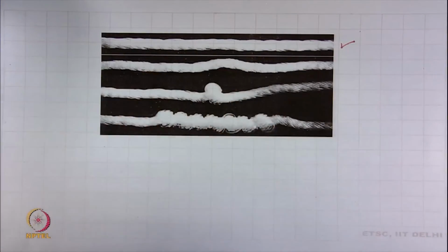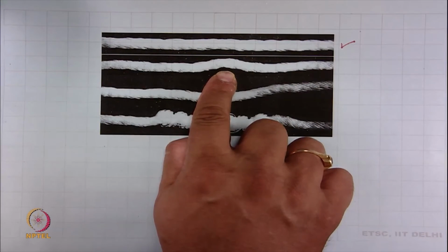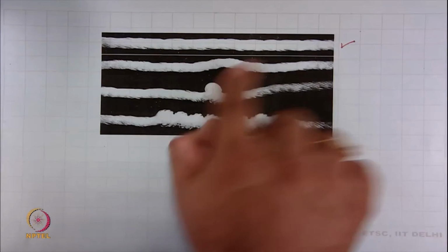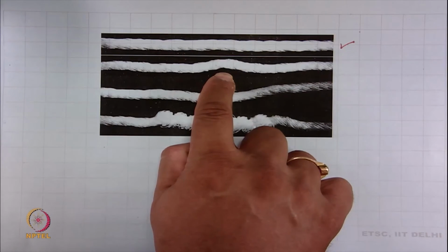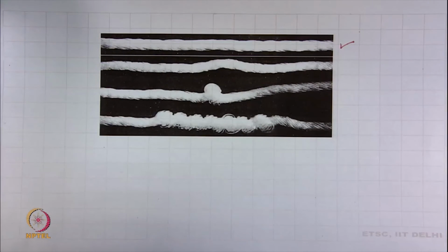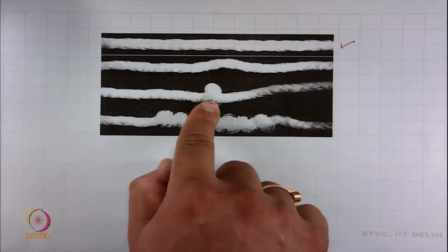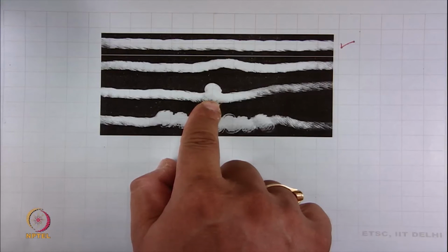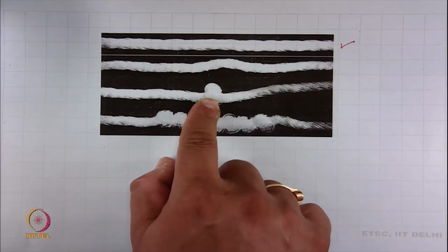So, the axis of the yarn will not be straight; first it happens gradually. First it is almost straight, then the axis deviates from linearity significantly. After a few insertions, you will suddenly see that the structure collapses. The fibers, the coils are not absorbed by the yarn, rather they are deposited onto the surface.